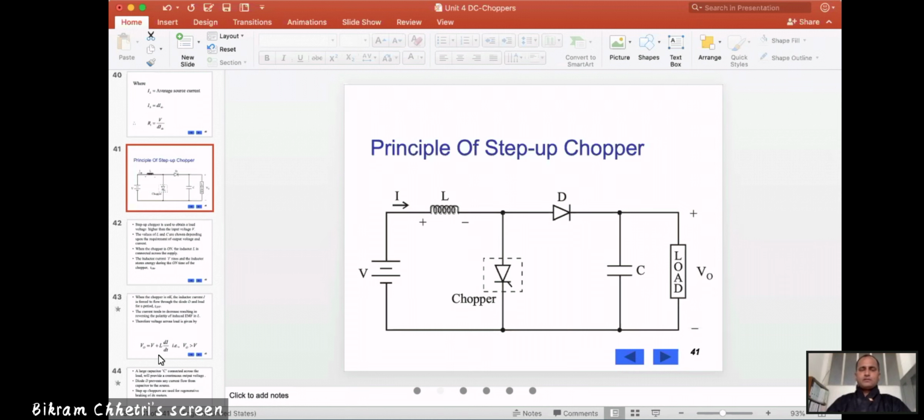What we have seen is that pulse width modulation is much more convenient than changes in the frequency. When we talk about frequency or modulation, we are talking about the time frame. If we keep the total time period constant and play with T on and T off, that we call the duty cycle: T on divided by total time T is known as the duty cycle.